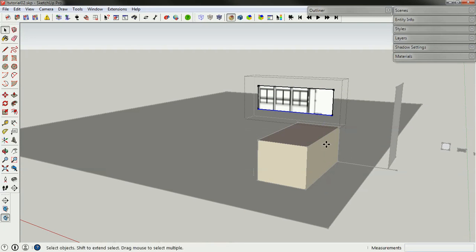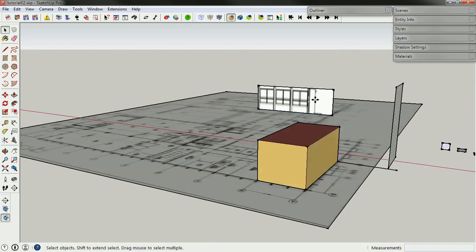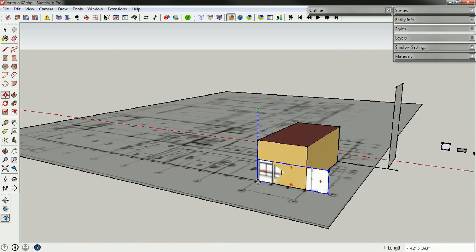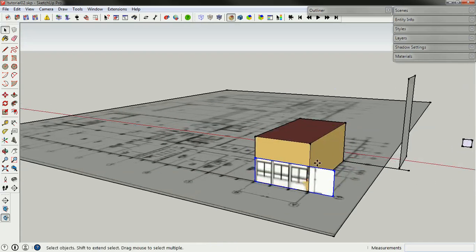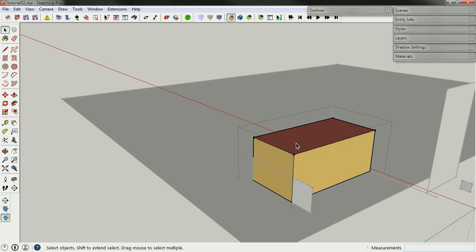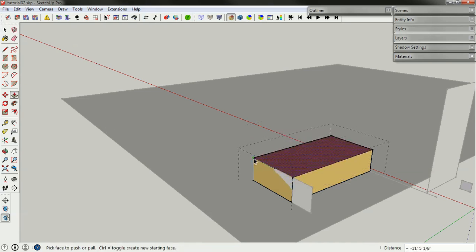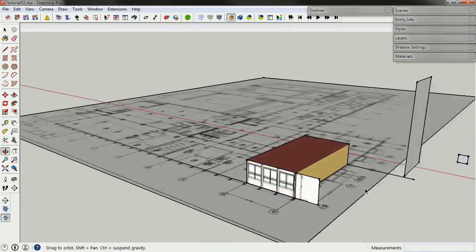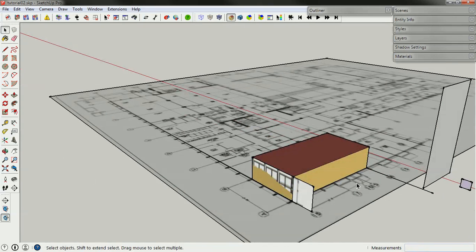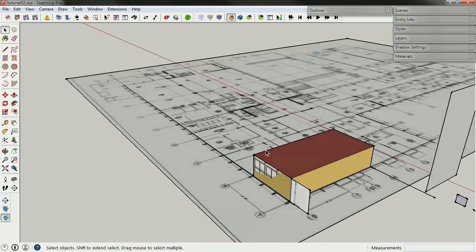So I'm going to assume that the top of the ceiling is somewhere around there, and the floor is somewhere around there. And that would be, how tall? 13 feet. I think that's about right. I think it's probably about 14 feet. So we're close. And now I'm going to align this vertically like so. And I want to align my zone as well. So I'm going to double click into the zone, press P for push, and then align the roof to that edge. So what I've made now is the boundary of my air. Remember, this is really an air model, and so the volume of air is contained by this box.